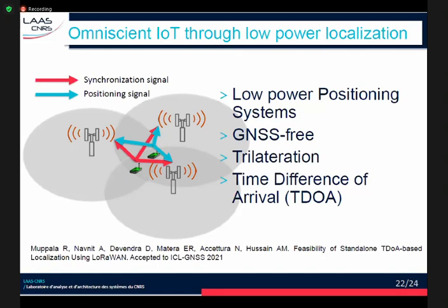The idea is that we have a device which is put in the middle of a triangle between the 3 gateways and transmits on the circumcenter. So when it sends the packet, it synchronizes the gateways because the packet arrives at the same time on the transceiver of the gateways. And after that, we receive another packet from somewhere else. So we don't know the position of that device. Based on the time difference of arrival with respect to the previous signal, we can reverse engineer the distance and so triangulate the signal.